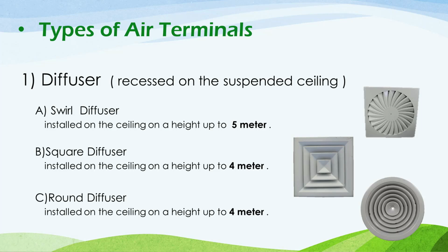But you may wonder now, why are the diffusers or the air terminals in general limited by a suspension height? This is because we need the air that goes from the air terminal to reach the thermal load, which may be some people, so we need that air to reach with a specific speed. So when the speed of the air is set at a value, then the cooling process will be done in the correct manner, as the room will be supplied with the required value of the thermal cooling air. But when the height of the air terminal increases by increasing the ceiling height, then the air will reach the people in the room with a lower speed, so the required air will not be sufficient to feed the thermal loads. And for this, we must decrease the air terminal height so the speed of the air will be sufficient enough.